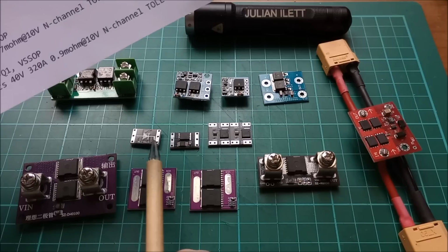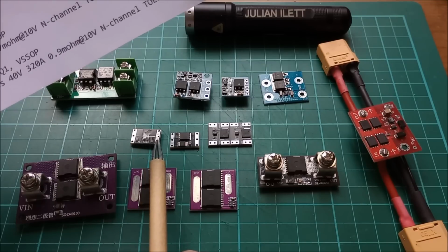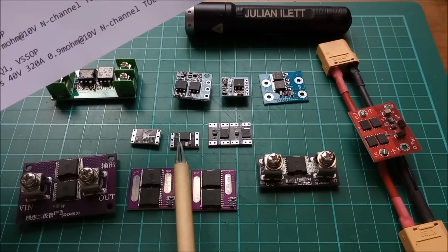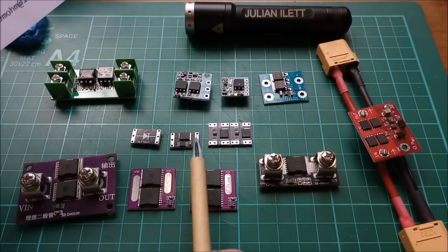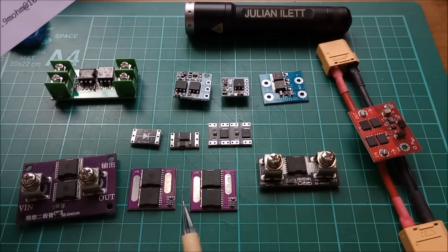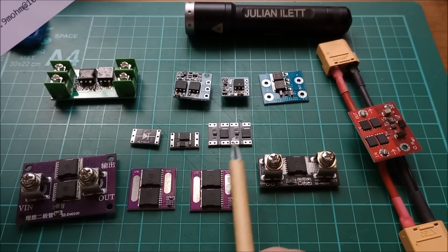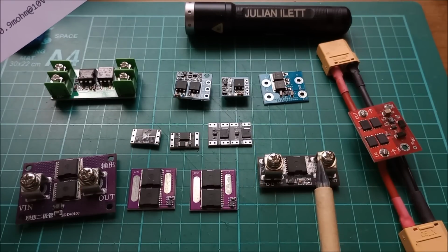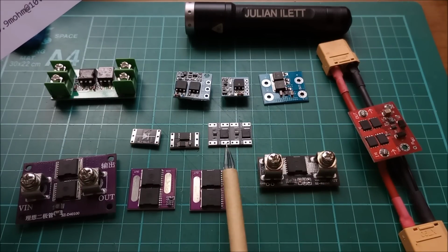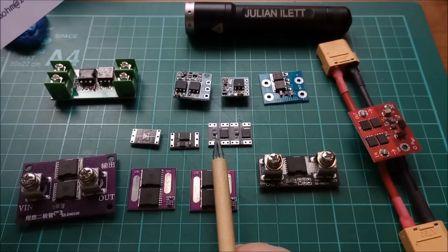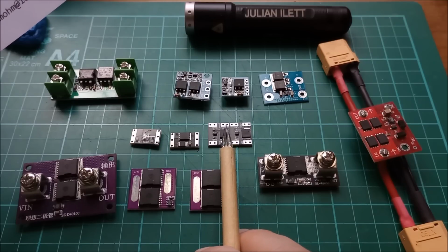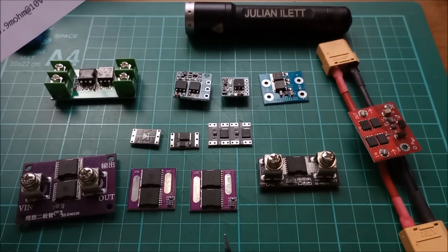Actually, I should point out that this is a 2-terminal ideal diode. So all you've got is anode and cathode. There's no ground reference point. So you can put this in systems that have a high voltage because you don't need this to reference to ground. Now that's different to this module and this module here, which use a chip which does require a ground reference. So you can see you've got anode, cathode, whichever way around it is, and 2 ground connections here. And the chip is actually powered by the voltage between probably anode and ground.